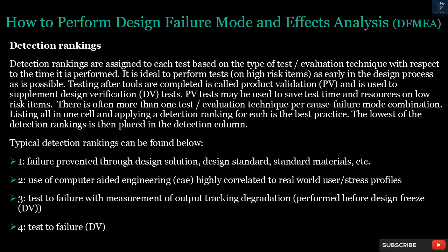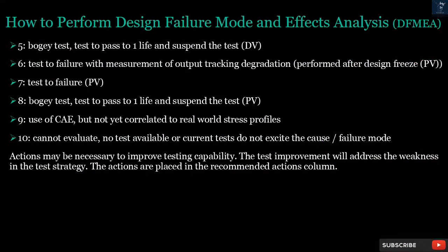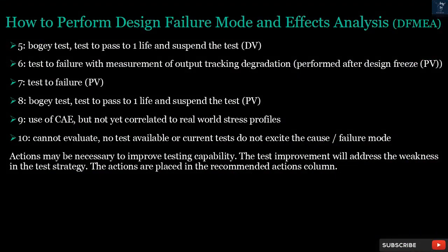1. Failure prevented through design solution, design standard, standard materials, etc. 2. Use of computer-aided engineering, CAE, highly correlated to real-world user and stress profiles. 3. Test to failure with measurement of output tracking degradation, performed before design freeze, DV. 4. Test to failure, DV. 5. Bogey test, test to pass to one life and suspend a test, DV.